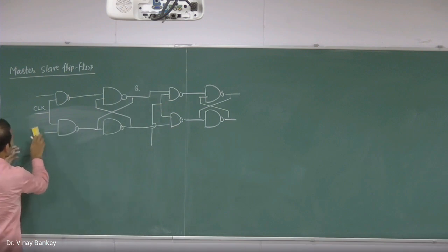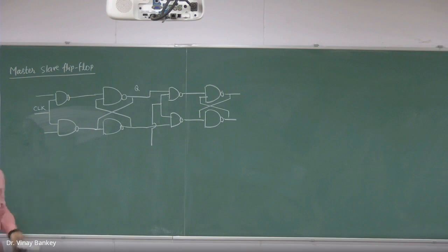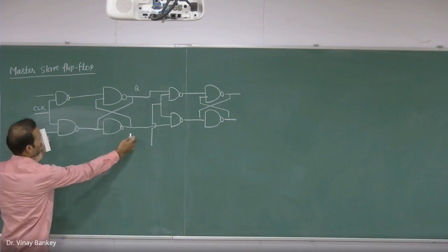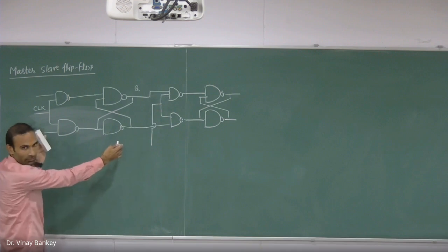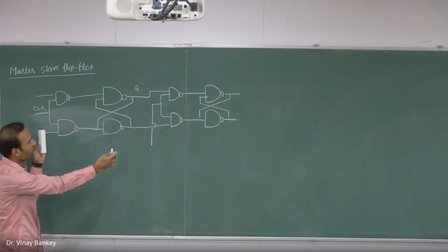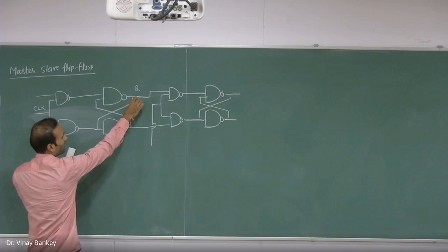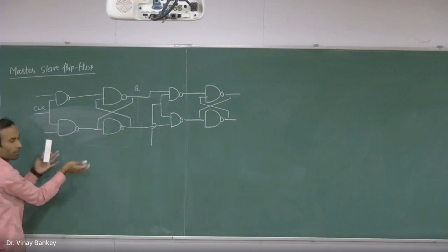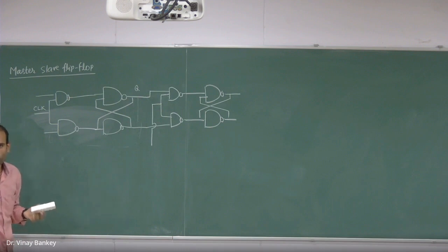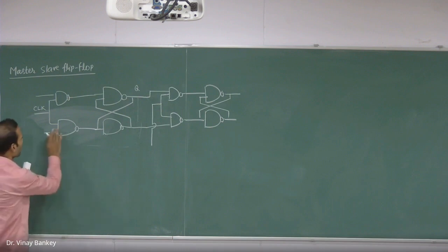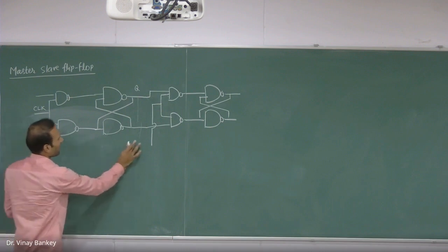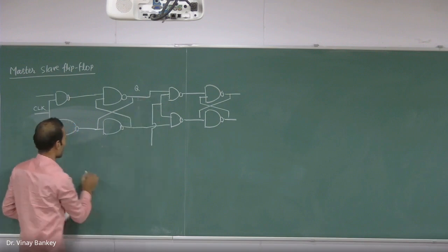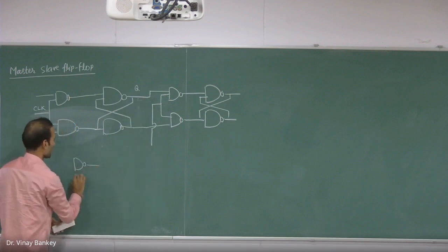Okay. Now, how to remember this circuit? What I have drawn here is the structure we used in the SR flip-flop, isn't it? And when we take the output and connect it to here, this will become the JK flip-flop. Do you remember this? And that's why we are having this race around condition. What happened when you have this arrangement?